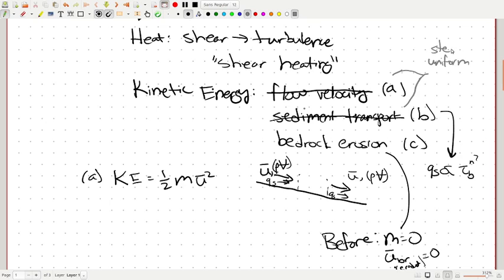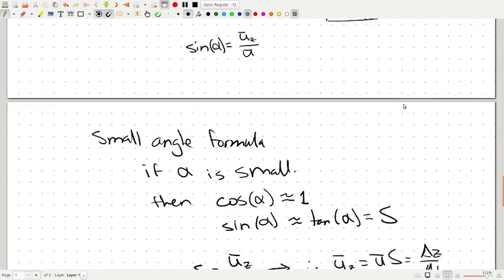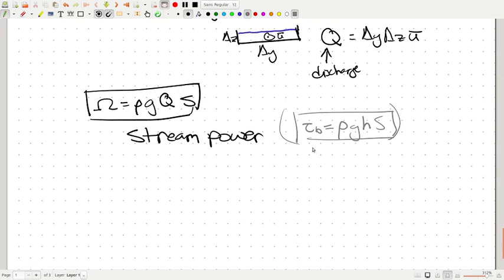And steady, so steady, uniform flow, meaning that there isn't any change in that flow with distance downstream, and that there also isn't change in time, and so therefore the real important one is this uniform bit right here. And this is the same thing as the depth-slope product for steady uniform flow, so I'm just going to make a big little note of that. And steady uniform flow conditions persist throughout most reaches of most rivers. It's a really good approximation as well.